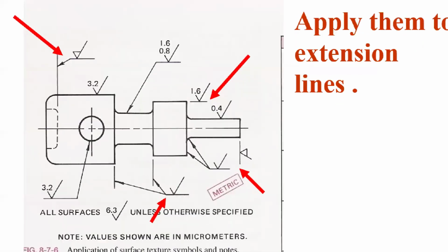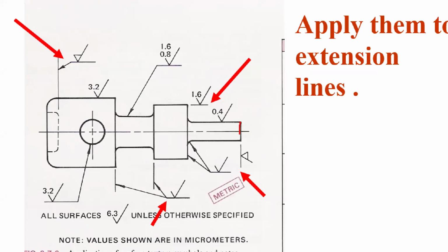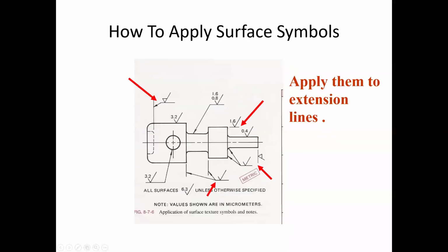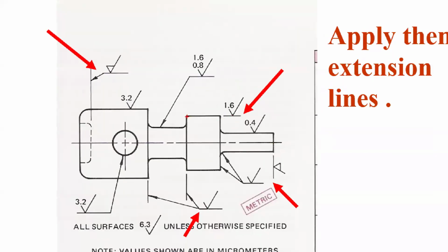So in this case, this extension is coming off this line right here, right? So what we're actually trying to control is the round surface on the very end. That's the surface that's being smooth. Does that make sense? Everybody get that? So let's look at another one here. The extension line is this edge, right? Which that edge is representing this entire cylindrical surface. That's the surface you're trying to control with that edge. Does that make sense?